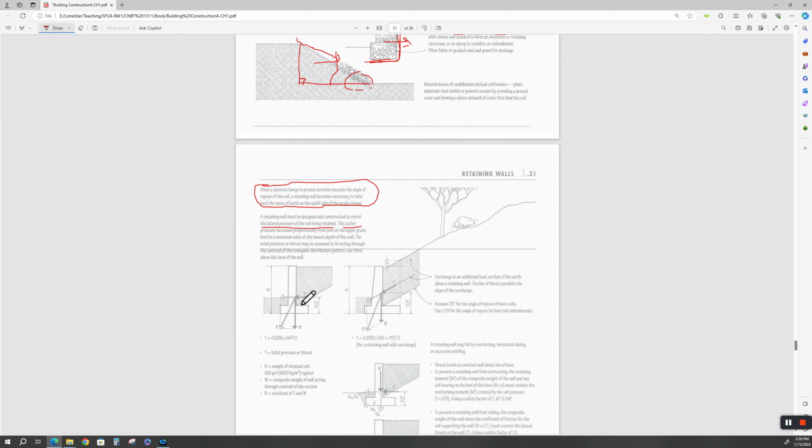Soil around here weighs about 150 pounds a cubic foot, which is the same as reinforced concrete. So we don't really worry about it when we're excavating for concrete footings and putting concrete back down, because we're putting back 150 pounds a cubic foot and we pulled out 150 pounds a cubic foot. There's no extra charge for that. But anyway, the retaining wall, the highest pressure is down here and the lowest pressure is up here.